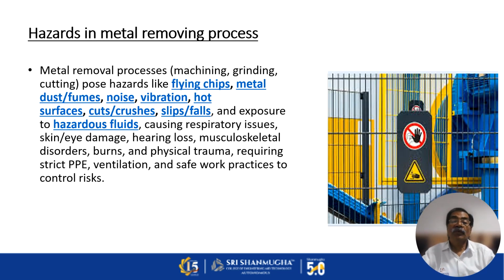Now, hazards in metal removing processes. Metal removing processes like machining, grinding, and cutting pose hazards like flying chips, metal dust or fumes, noise, vibration, hot surfaces, cuts and crushes, slips and falls, and exposure to hazardous fluids, causing respiratory issues, skin or eye damage, hearing loss, musculoskeletal disorders, burns, and physical trauma, requiring strict PPE, that is personal protective equipment, ventilation, and safe work practices to control risk.